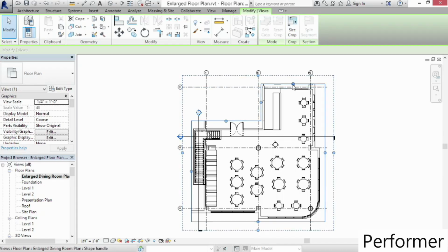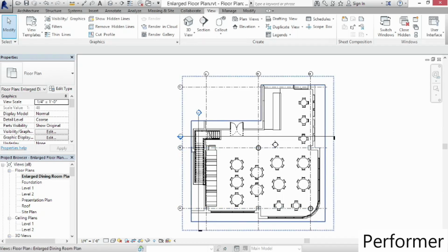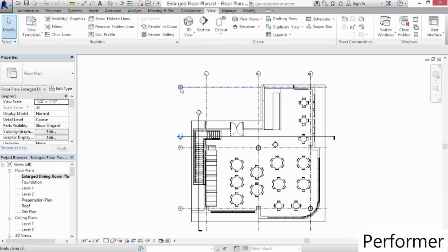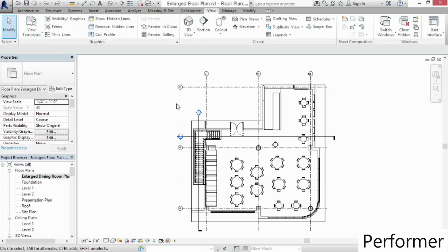So I will just make any little adjustments here just to fine tune it slightly. There's a few other things that you'll notice here that we might want to address. For example, these grid lines here extend all the way to the virtual rectangle here, and that's simply because the behavior of grid lines is for them to remain lined up with one another. So A and B, it makes sense for them to go a little bit past the callout boundary, but C, maybe not so much. So what you can do here is you can select grid line C, and then you want to be careful not to start to drag it, because if you drag it, it will drag all of them. I'm going to do Control Z and undo that.